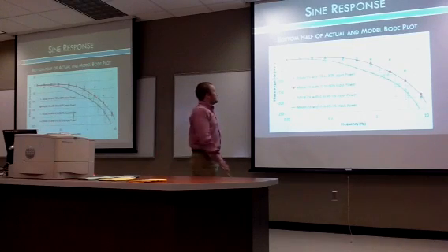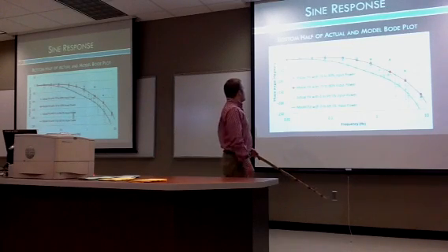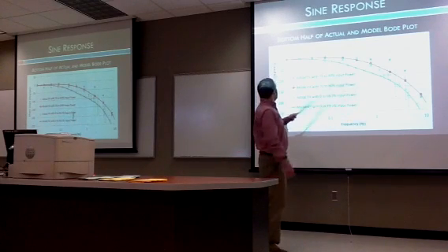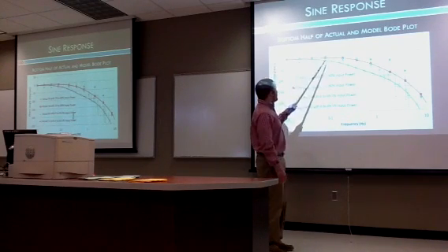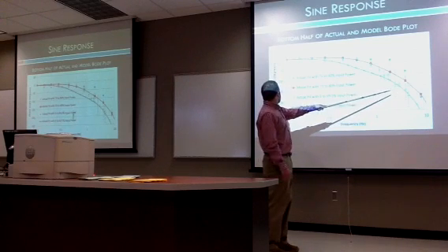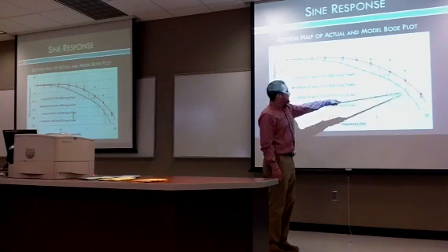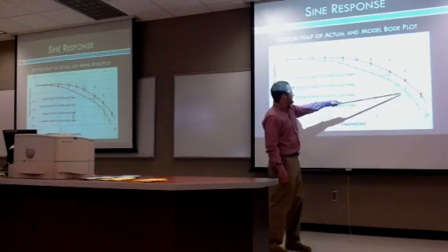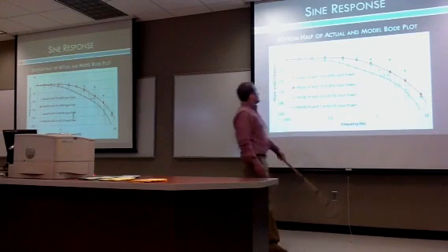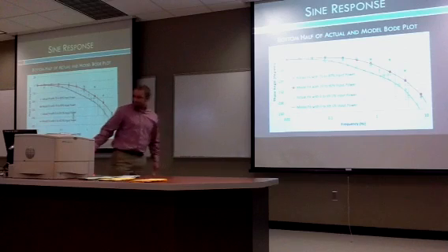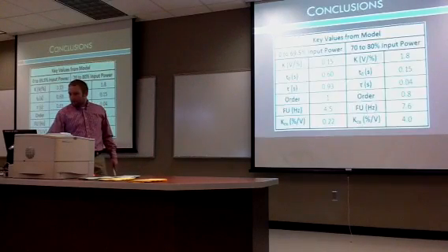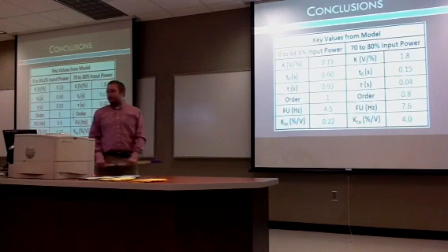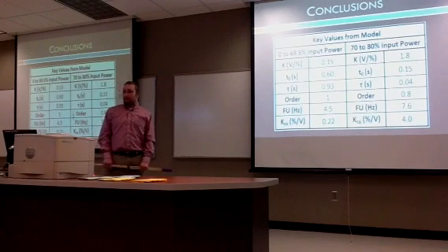What's important here is that when we model this curve, we change the parameters so that you want them close up here again, but then when you get to negative 180 degrees, you want the two to cross, which you can see this would cross right about at negative 180 degrees, and so does this. And then we have all the means to be able to solve for the different key values for the model.